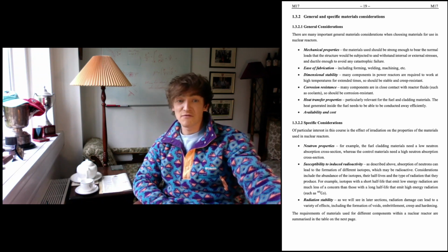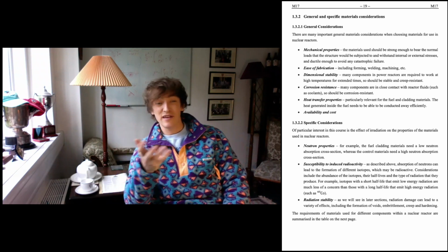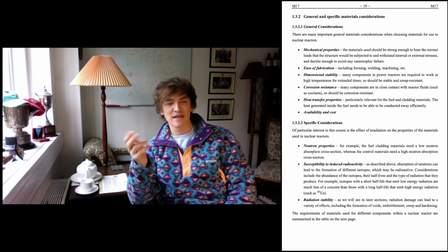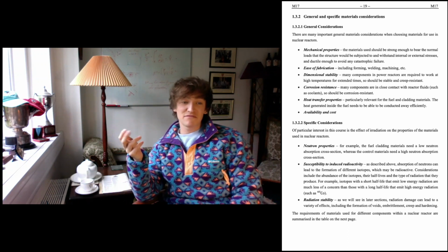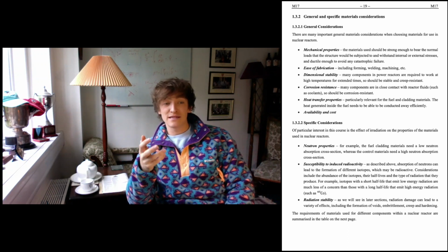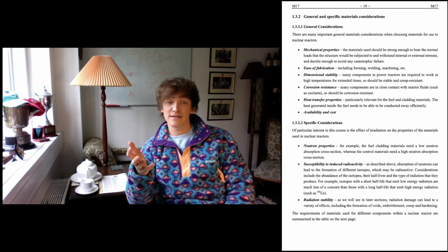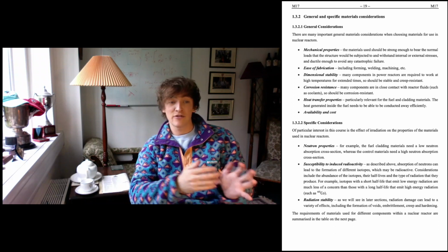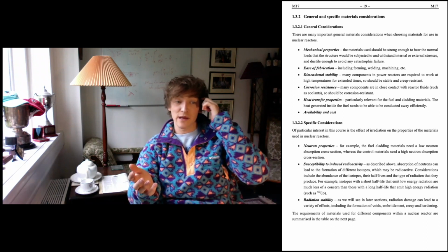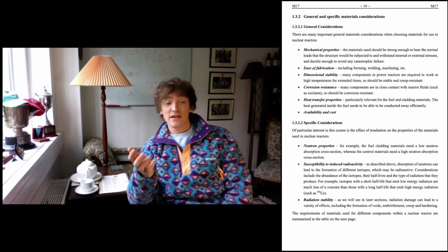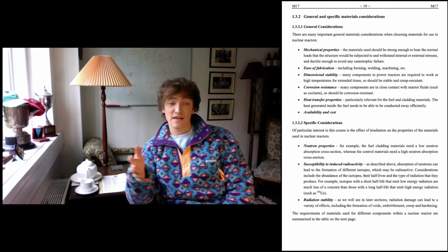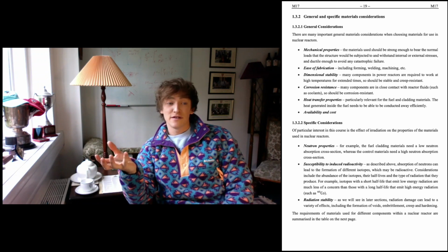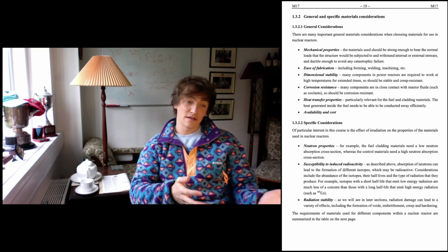Can it be welded, formed, machined, graphene coated? Could we make it out of graphene? No, I think we'll give that a miss. Dimensional stability. Can a component maintain its operation throughout the life of the reactor? Can the material withstand the high temperatures it's subjected to, or will it creep or undergo phase transformations? Similarly, corrosion resistance. Can the material withstand the environment it's in? Will it react with the reactor coolant? Does it need to be corrosion resistant?